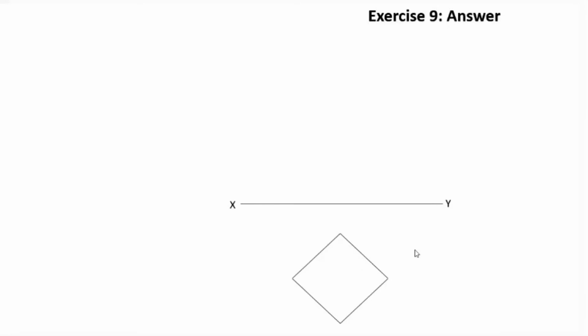Otherwise, when we cut the cube with a plane which is perpendicular to VP, we may not be able to cut all the 6 faces. So we place it like this, with all the edges equally inclined to VP, then name the edges. Now the front view